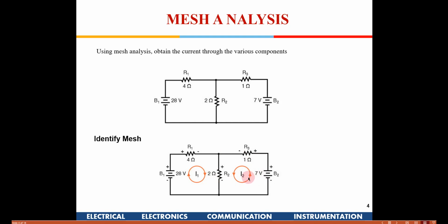Nevertheless, I have taken this as anti-clockwise direction, and this as clockwise direction. It is just a starting point. Whichever way you start, if you are careful with the signs of these currents while framing the KVL, you will get the same answer irrespective of how you start.